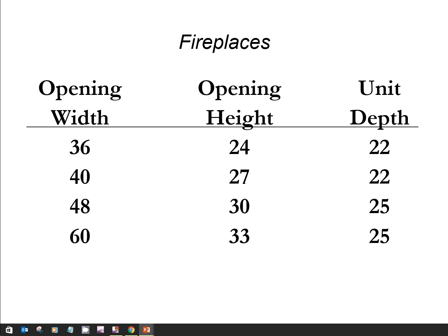A smaller room gets a smaller fireplace. These are some typical sizes for a masonry fireplace, and you can get prefab ones also that come in standard sizes. But a normal fireplace size is going to be this 36 to 40 inch width, and it gives you a height and then the depth of it.